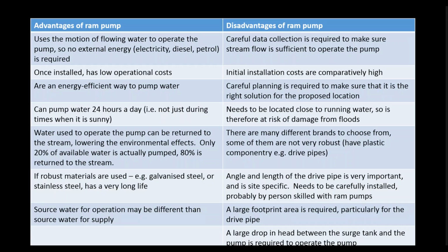Another challenge is that by its nature it has to be located close to running water. So during periods of rainfall, if it's going to flood, then the pump is at risk of being damaged due to floods. We've had some issues with some of these pumps being damaged after or during a flood, particularly the surge tank, which is a little bit lighter. It's only made from sheet metal and may be easier to damage.